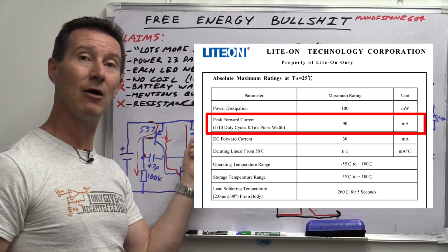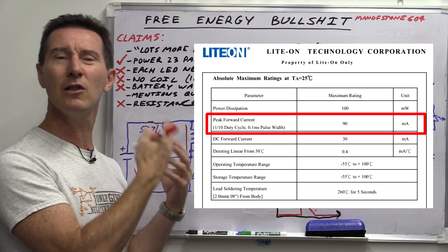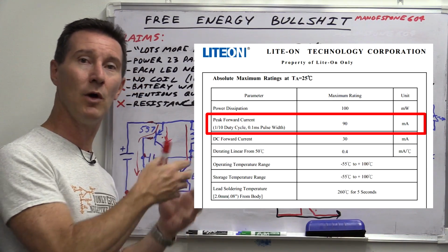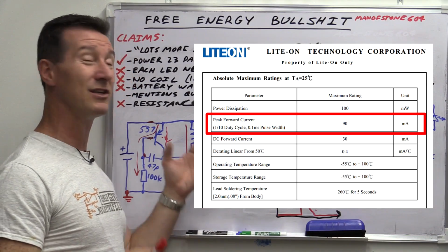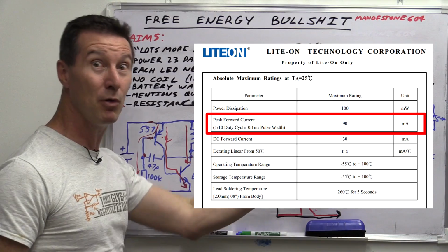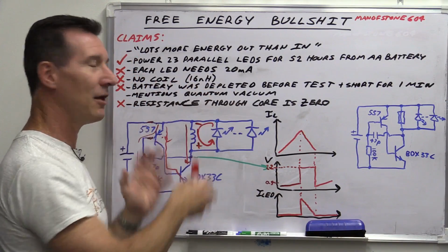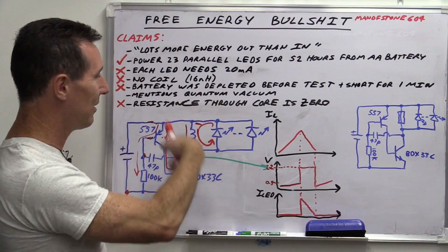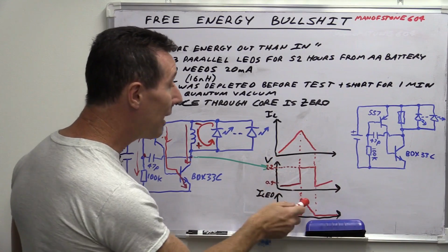They might have a maximum continuous current rating of 20 milliamps, for example. A lot of them have a pulse current rating as well for a certain period of time, but you've got to be very careful not to exceed that sort of thing, it can drastically limit the life of your LEDs. This is a really poor engineering solution. There's no current limiting resistor. You don't know the boundaries of your current conditions, and it's just horrible. But anyway, that's how it works.